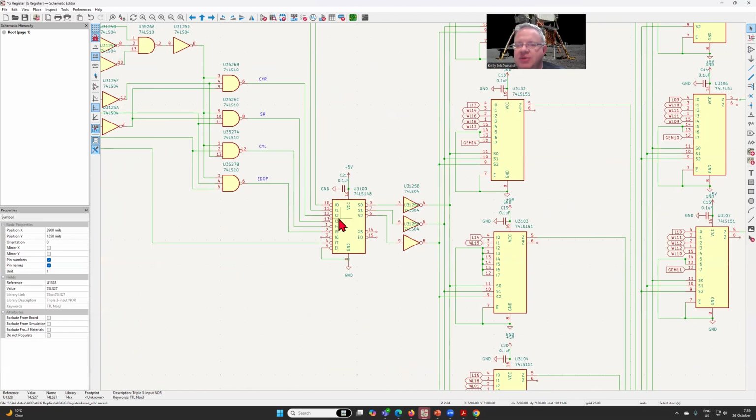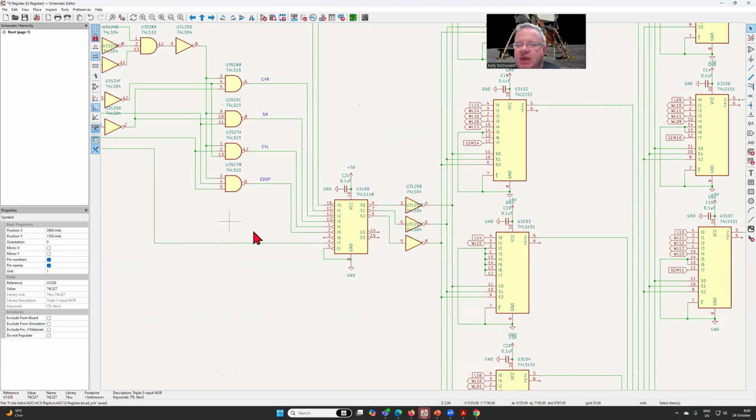And so this is basically what, by pulling low either pin 0, 1, 2, 3, 4, 5, 6, 7, it will generate the appropriate sequence values that I'll need. Now, in this case, I do need to invert them because you can see on the 148, they come out inverted, whereas these are not inverted. So we've got those bits there flipped.